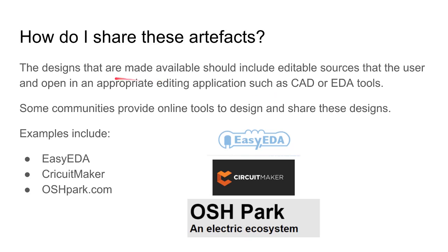So you find a lot of communities online that provide online tools that let you design and share the designs at the same time. For example, EasyEDA is quite a popular, easy to use software tool that's based in the cloud that lets you, without downloading any software, do it on their website. You can build your schematic, you can lay out your board, and you can edit your bill of materials from where you can directly order that board that you designed online and pay for it and have it delivered, all from that one simple to use website.